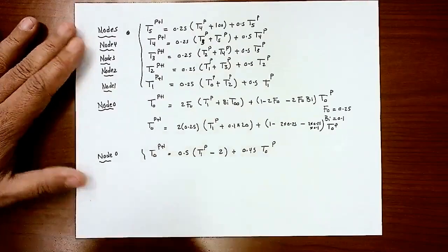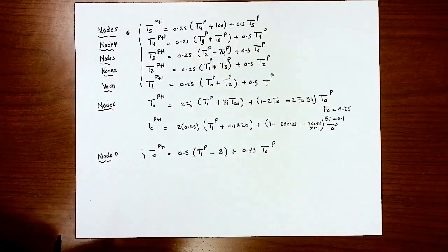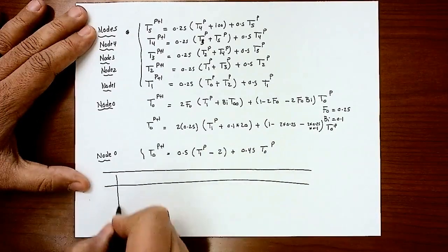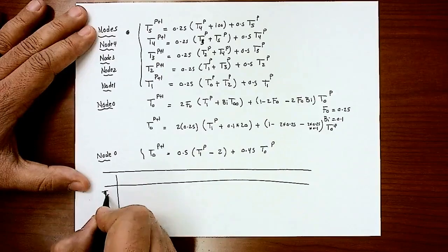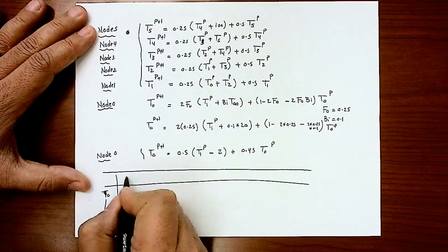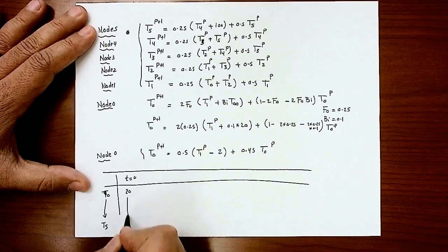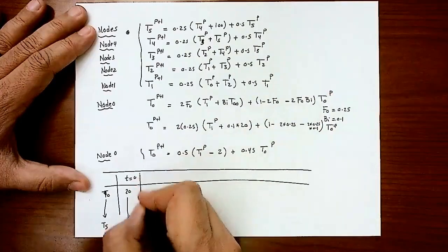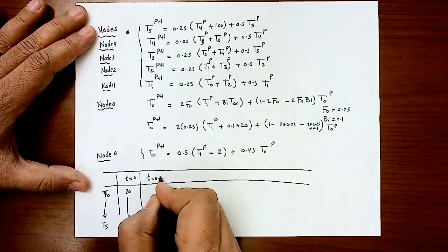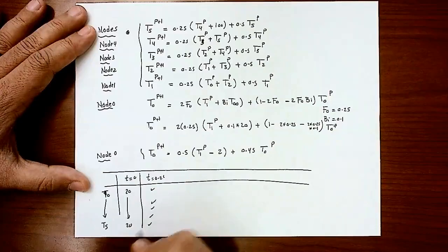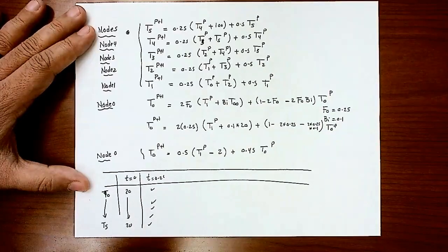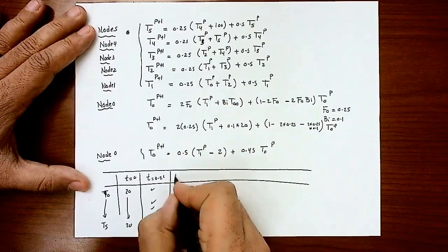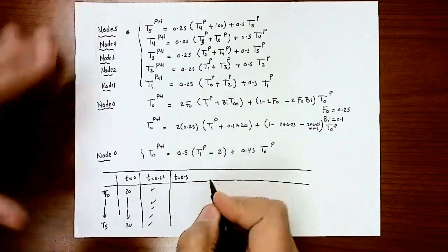In addition to this equation, these are explicit methods. You start with your initial values. So you list your nodes T node all the way to T5. Then at time equals 0, you guess everything to be 20 degrees. Then you substitute in the right-hand side. Then you calculate the data at time equals 0.25. You have the data values here, right? Then this is the data that you're going to use for the next time step, which is 0.5, and so on.